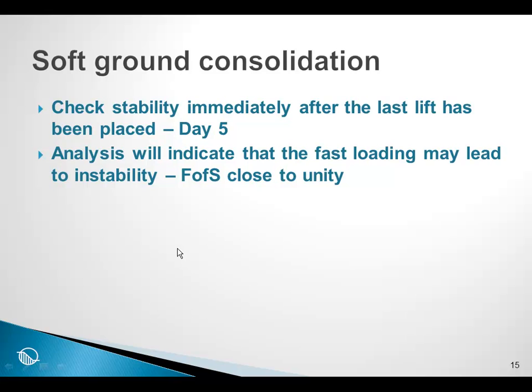And what we then want to do is look at where we have the maximum excess pore water pressure conditions, and to check the stability. As it turns out, it will be immediately after we place the last lift on day 5. As we will see, this fast loading will lead to a factor of safety that is close to 1, suggesting that this rate of fill placement is too fast to maintain stability.